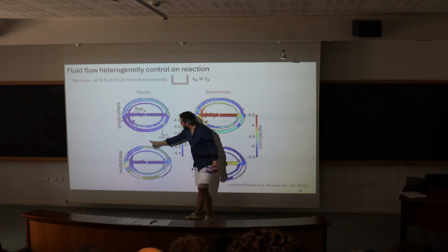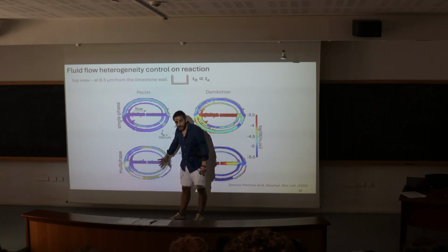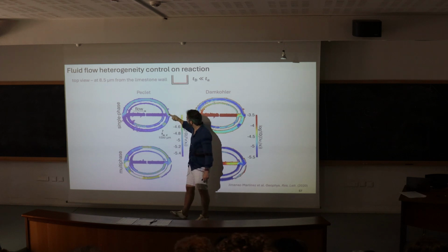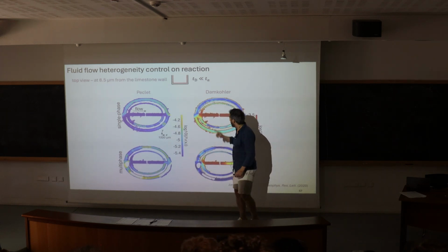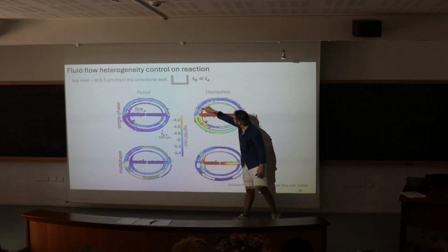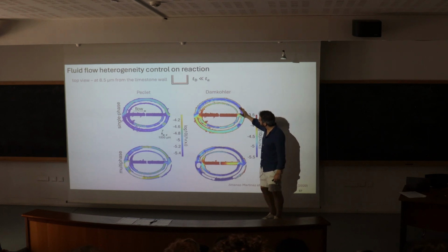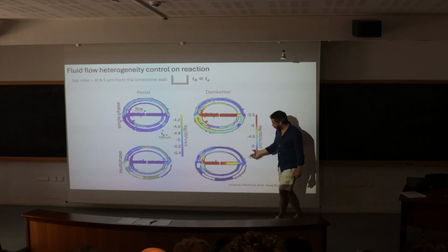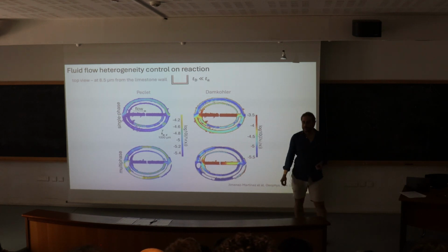If you see, this image has much more homogeneous Peclet, and we have demonstrated this statistically, than this one. This one has a Peclet which is in one channel which is completely different than the rest of the channels. So the dissolution, and also if you go to the Damköhler, is even more evident. You see Damköhler here is for single phase. Damköhler is completely different in this channel where you mainly have the dissolution than in the rest of the channels. While if you go to a multiphase flow system, Damköhler is more or less the same everywhere.